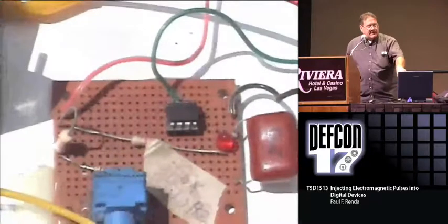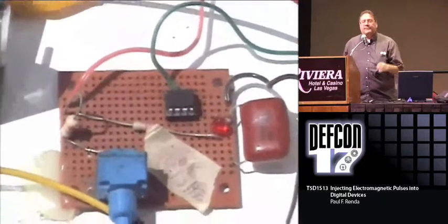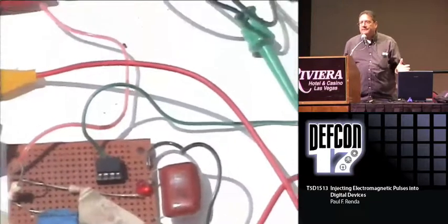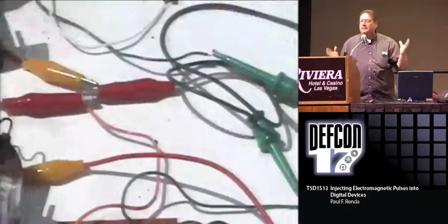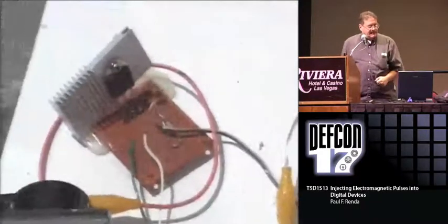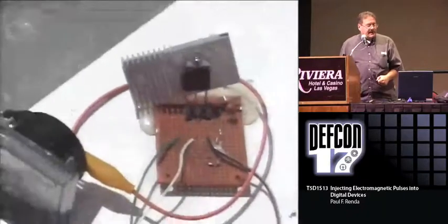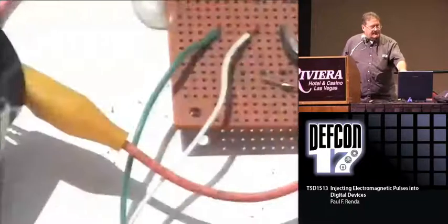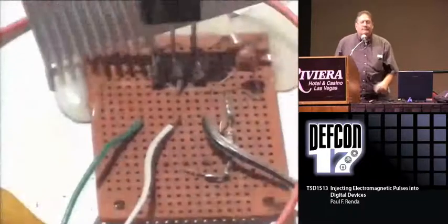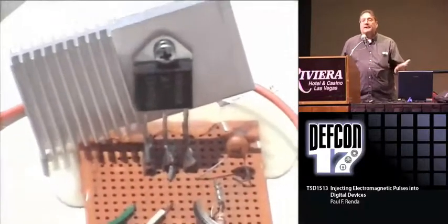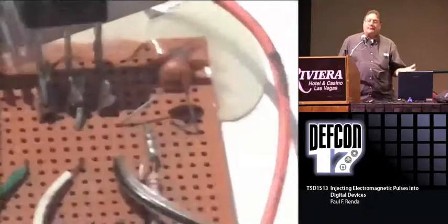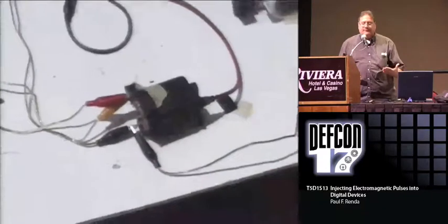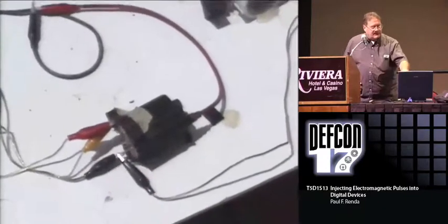Now I'm showing you a control circuit for an integrated circuit called a 555 timer. Millions of references on the internet. You put in Yahoo, Google, whatever, millions of references. It creates a pulse, and it's fed into this thing called a MOSFET, a type of power transistor. It sends its pulse to that green wire. The green wire is attached to the gate of the MOSFET, turns the gate on and off. In other words, I put high voltage, battery voltage across this transformer.